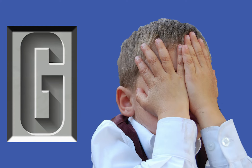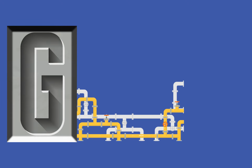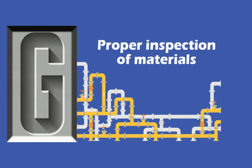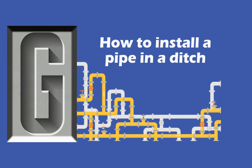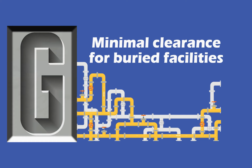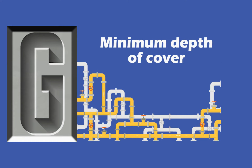Next is Subpart G, as in, good lord, how many subparts are there? Don't worry, the end is in sight. G lays out all you need to know before you start laying out transmission lines and mains. Things like proper inspection of materials, repair of steel and plastic pipe, how to install a pipe in a ditch, the minimal clearance for buried facilities, and the minimum depth of cover.